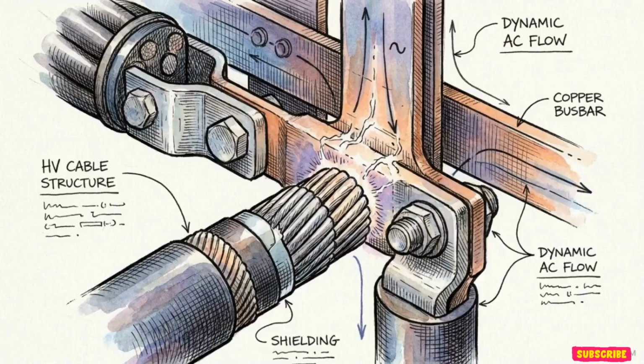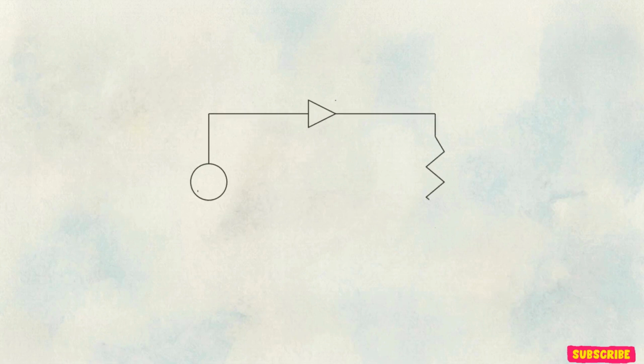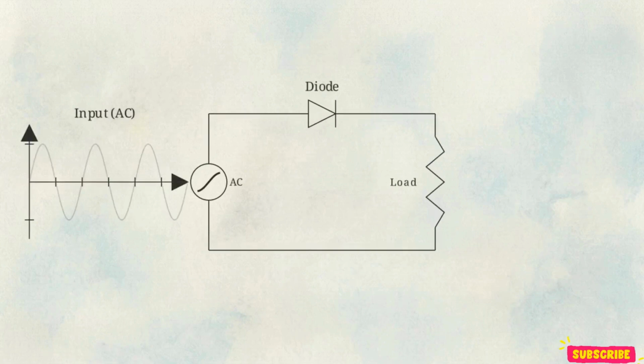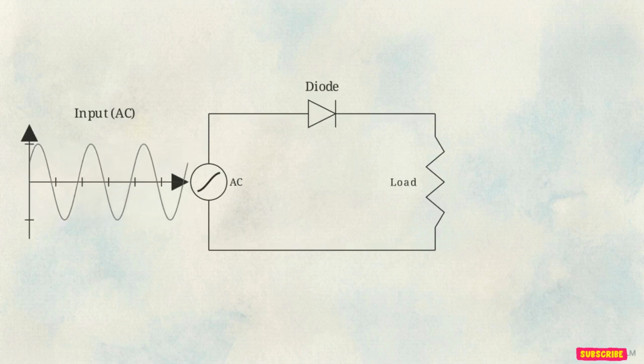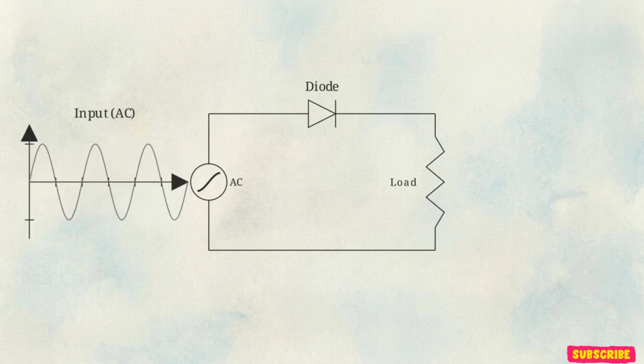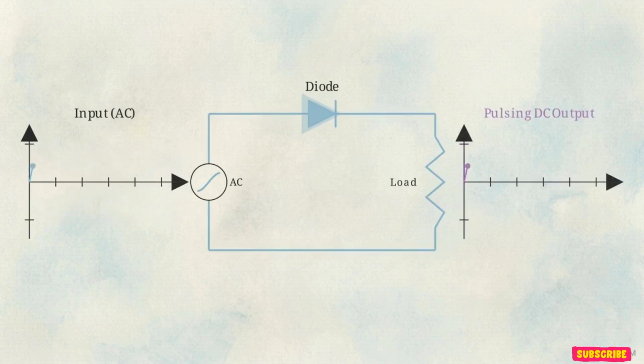Real-world electrical systems are highly dynamic. Voltages do not stay constant, they shift and reverse continually. This is a schematic for a half-wave rectifier. It is the most fundamental circuit application for a diode, used to manage those shifting voltages. The graph on the input side displays a standard alternating current sine wave. The voltage is constantly swinging from positive to negative, reversing polarity dozens of times a second.